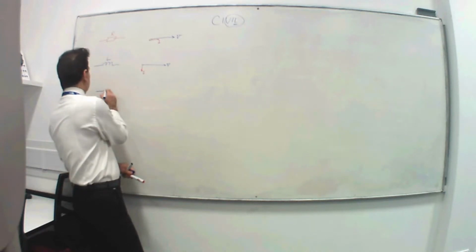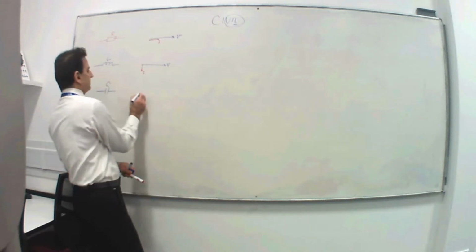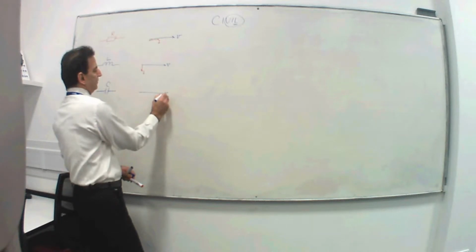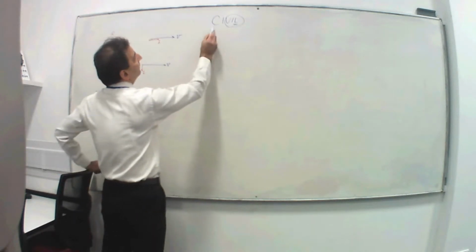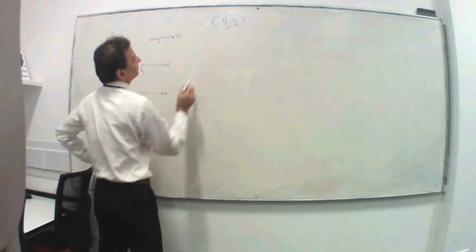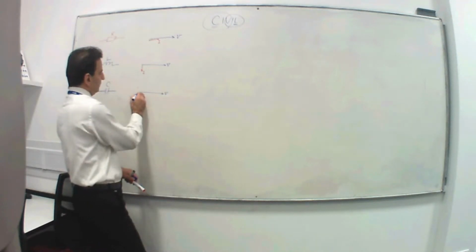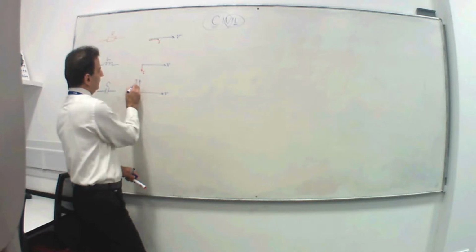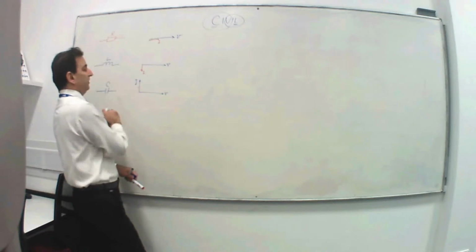And for capacitive, purely capacitive circuits, if that's voltage, again looking at that, if it is capacitive, current is leading voltage. So current would be up here by 90 degrees if it is purely capacitive.